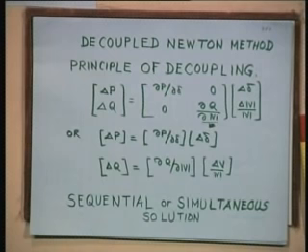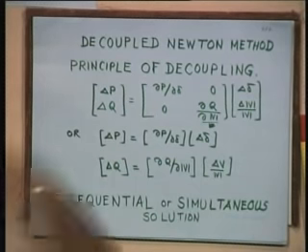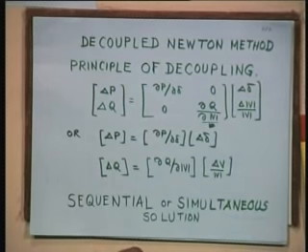Now next, there are so many load flow methods, starting from Gauss, Gauss-Seidel, Newton-Raphson, approximate load flow which we have done once, where we ignore resistance, so you can get a closed form solution if you want to. Then there is a decoupled load flow which we are going to start soon. Then there is a fast decoupled load flow, then there is a super decoupled load flow, like super express and so on. Then there is a second order load flow method, and finally we will have an optimal load flow method.